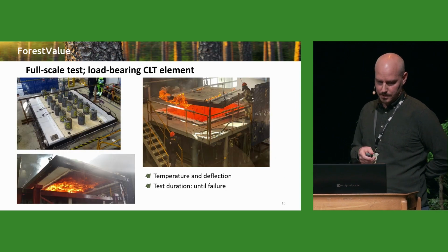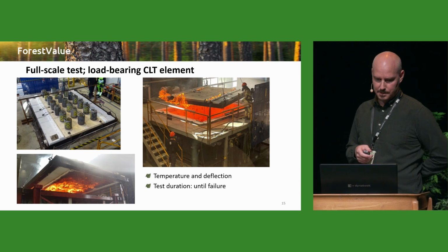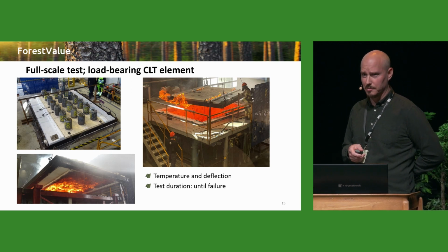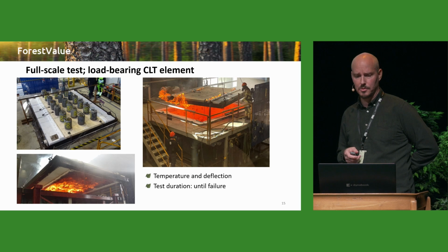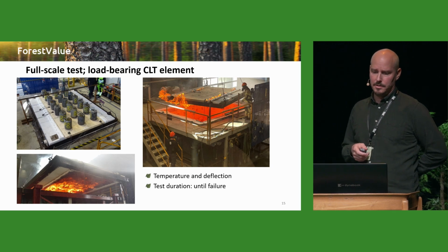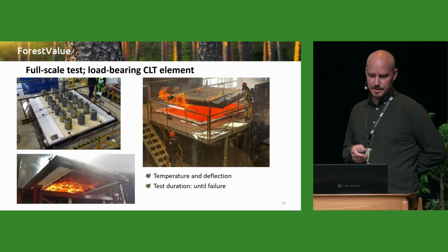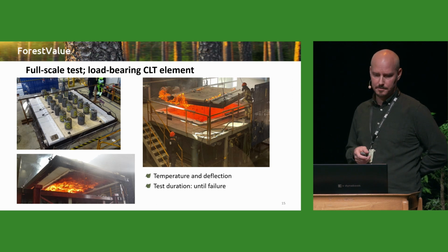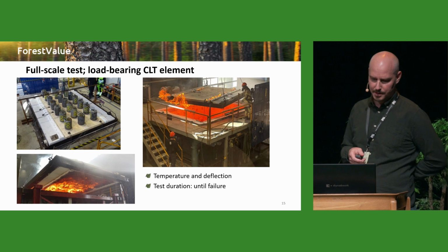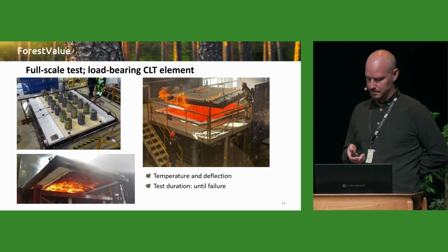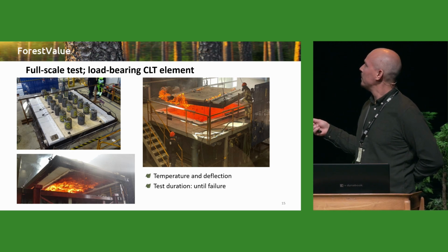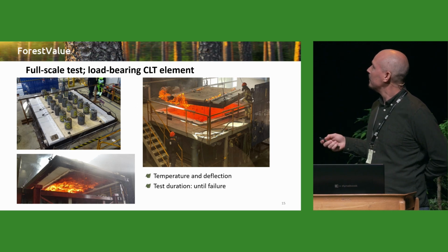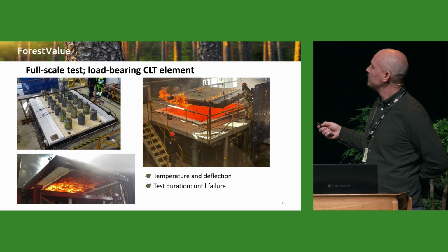Moving on, we did also the full-scale tests, and these are very similar to how to test load-bearing constructions in fire resistance. And for this particular test, this was a CLT element. It's roughly 4.5 meters long here and 2 meters wide. And we have dead weights on top of it.